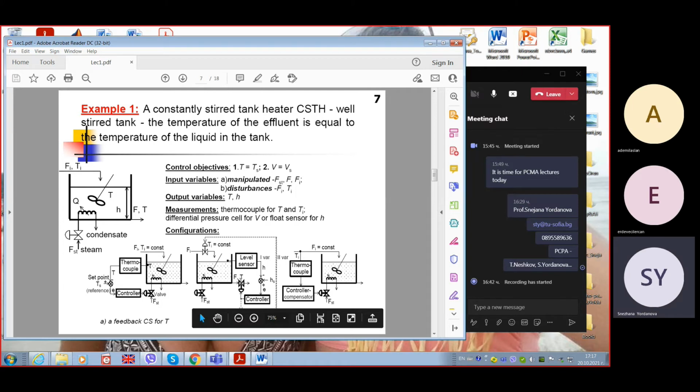That means we have to decrease this opening, less liquid to leave the tank. But if we have this variant of application of control action, for small level, we need more inflow. So the control action should open more this valve, so as to let more liquid inside the tank. So we have a process which is related with the stabilization of two variables, temperature and level.